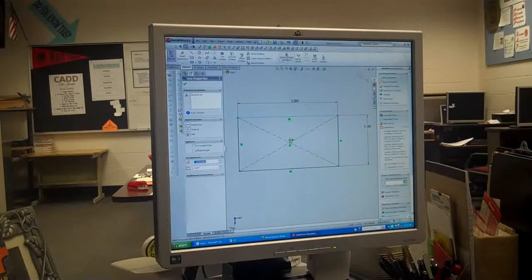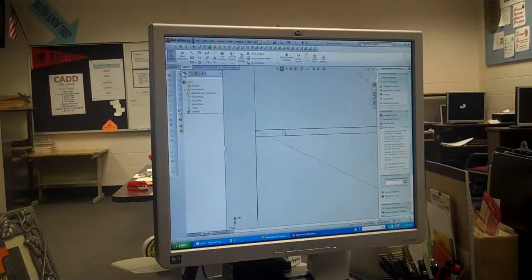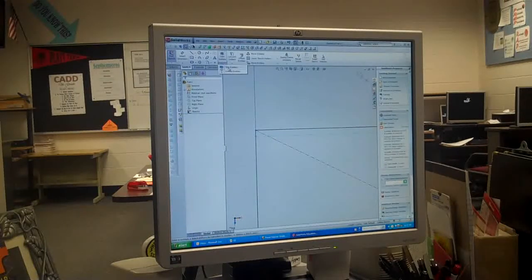We'll take this edge, we're going to offset it 0.025 millimeters, reverse it, shut off chain, happy check mark, zoom in, grab that, change it to construction, and then we are going to trim and create a small gap.